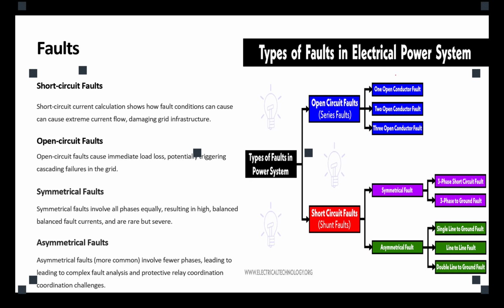But if we just formulate our response to a disturbance based on an ideal protection, that means any harsh disturbance, even if it's very short, would result in the protection activating and disconnecting certain components, which is also going to affect our load demand balance, meaning it would affect the stability of the system.